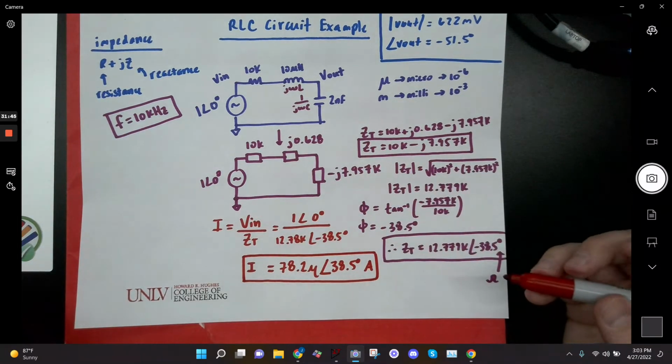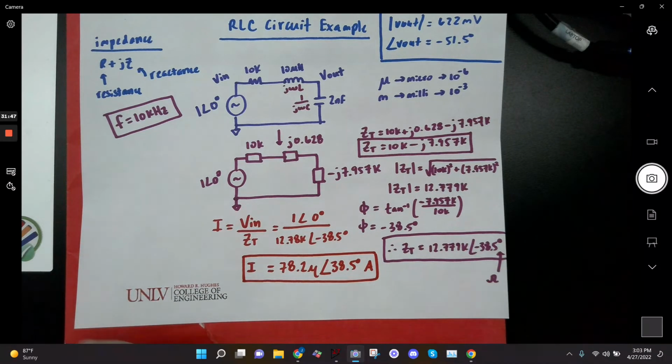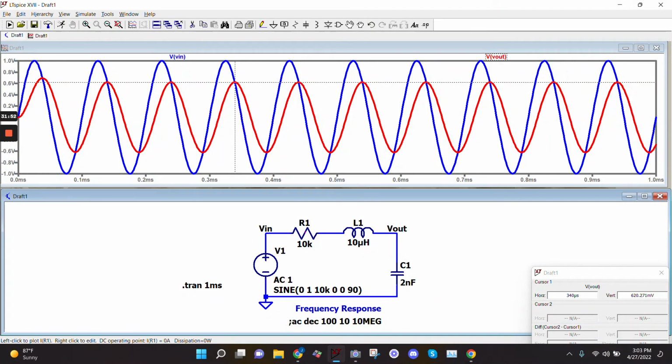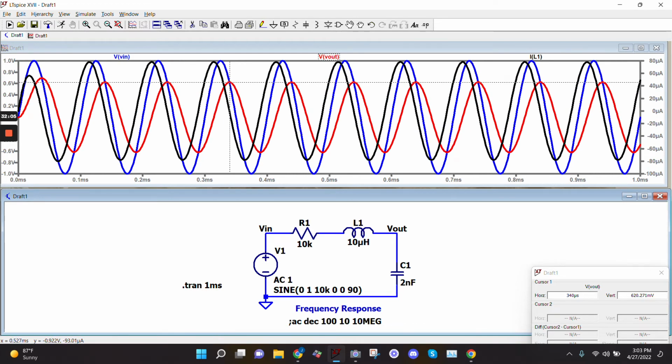Anybody get that? Let's go check SPICE. Someone had a problem with this. Does everybody notice the arrow's pointing the wrong way here? If you don't flip that, you will get the wrong values. But again, you don't have to take the current there. You can take the current from either of the ones that are actually pointing the right way. Okay? I got 78.2 micro.